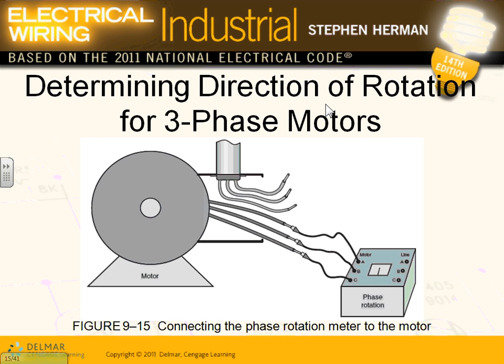The second thing that you guys talk about here in the presentation is the direction of rotation. Direction of rotation is very, very important. Imagine a machine where the conveyor is supposed to go this way, and if you flip the phases, now it's going the other direction. Bad news, unless you want it to go both ways. Imagine a fan that's supposed to blow the air out. You rotate it, now it's blowing the air in. Now it's bringing the air and the smoke in. So rotation of a motor is a big deal.